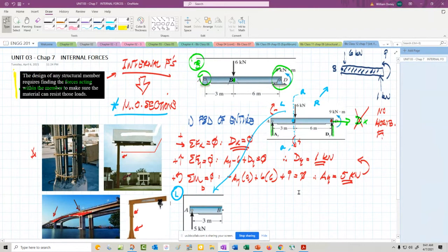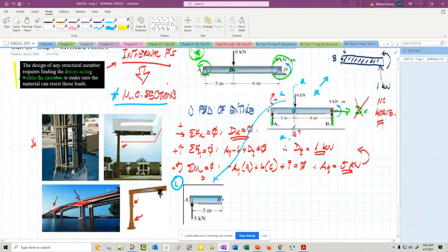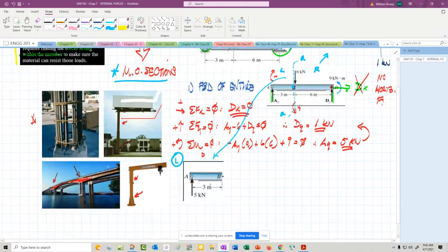Now, if you remember when we cut members in half, the ones that are tension and compression, there was internal loading that then became external loading. So when I make that cut at B, there's some loading internally that now becomes external loads that I have to include. And I'm going to draw those now. Just going to make this a little bigger so these come out nicer.